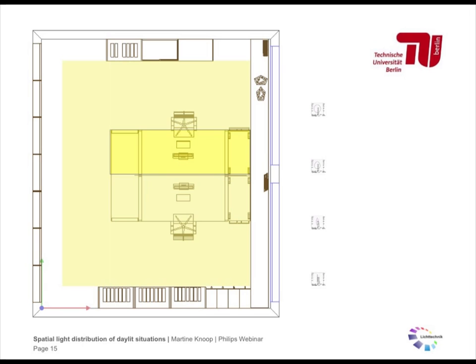If I now look at the next solution, as you can see on this screen, I could focus on my task area, reduce the lighting in my surrounding area to, for example, 300 lux, and the remaining area, which is the background area, can have an even lower light level. So according to the standards, that's possible, and that's best done with directed lighting solutions. So it really offers LED solutions another way of saving energy. What happens with the lighting in the room?